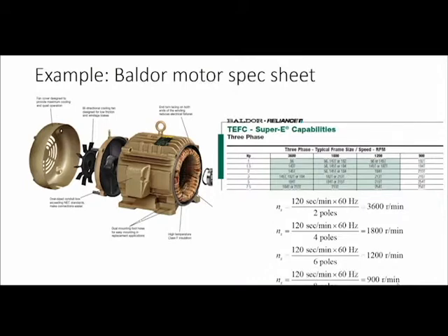Now, you don't have any real control over this once it's already spinning at that speed, at least not much control over it. So it would have to be an application where you do want constant speed from your system. You can then use gearboxes. Say you don't want to spin at 3600 RPMs, you can use gearboxes to have it spin at the speed you want, right, to gear this rotation here.